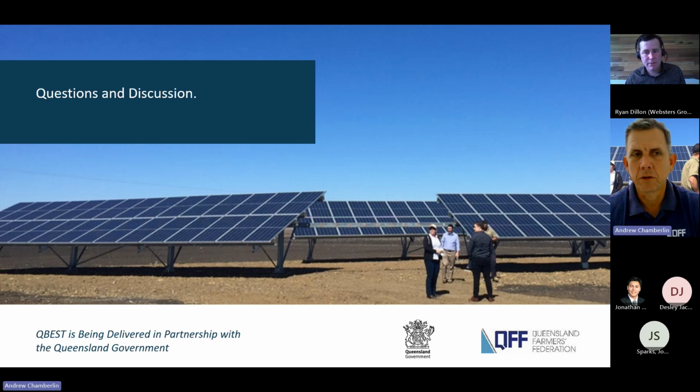That's right. I think we saw one of the energy audits that we did earlier where there was a payback period of about 8 years on the upgrade of all the cold room fans and condensers, which the farmer said was outside their target range for investment. However, it was a fairly old system, so they kept that audit report in the top drawer, knowing that the cold room was probably not too far from end of life. So they had the specification there for when that did happen, or when a grant program came up